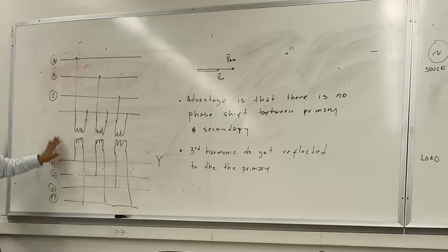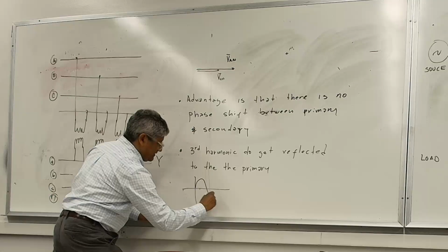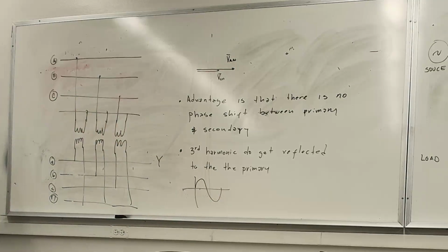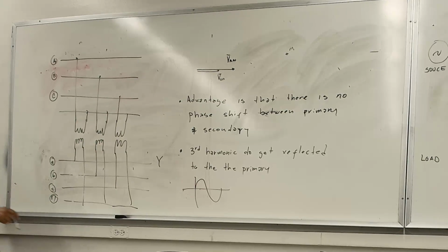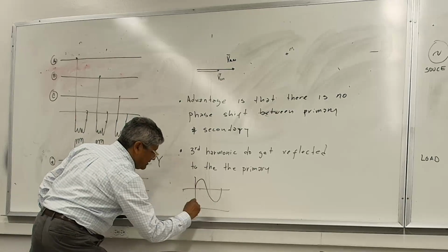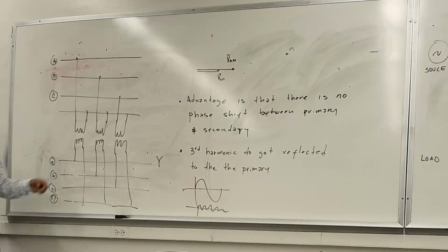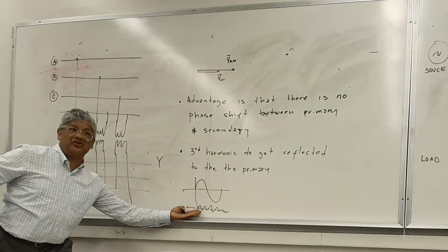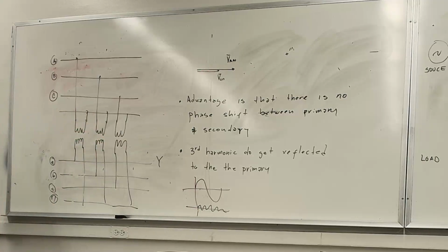And in many cases, this transformer had not necessarily been designed for that. Because as I said, the transformer is being designed for a 60 hertz waveform. But these nonlinear loads are producing, say, third harmonics that are really high, right? So 120 hertz on top of the 60 hertz. This is a current. You still have to deal with a current, right? So that's one of the disadvantages.